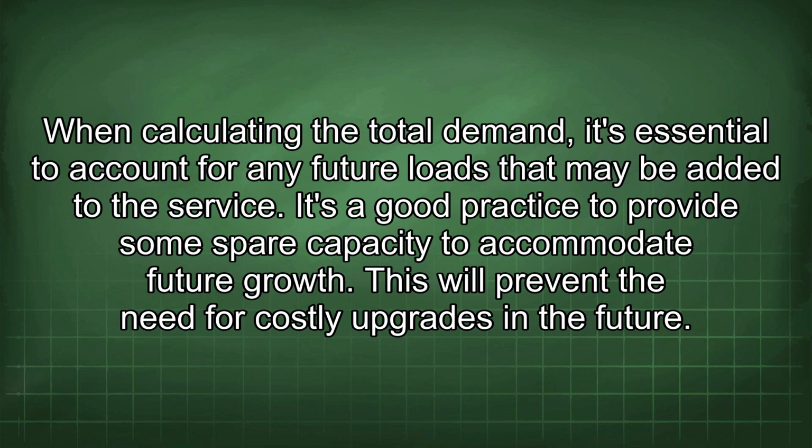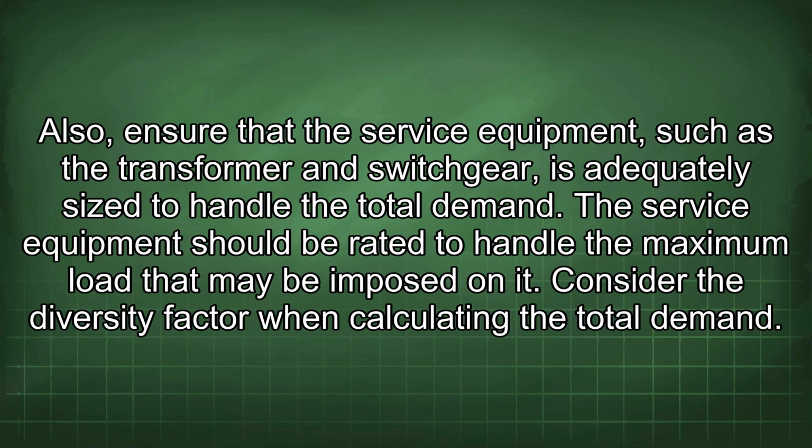When calculating the total demand, it's essential to account for any future loads that may be added to the service. It's a good practice to provide some spare capacity to accommodate future growth. This will prevent the need for costly upgrades in the future. Also, ensure that the service equipment, such as the transformer and switchgear, is adequately sized to handle the total demand. The service equipment should be rated to handle the maximum load that may be imposed on it.